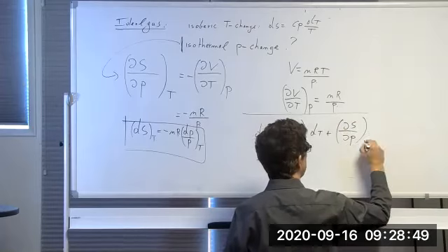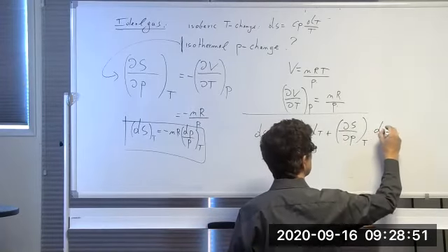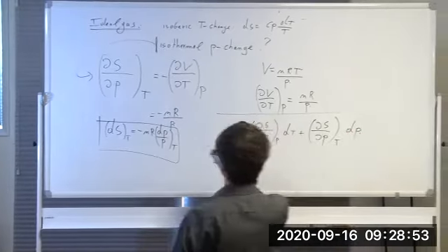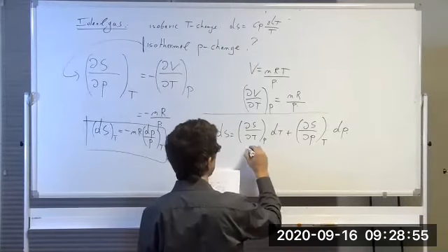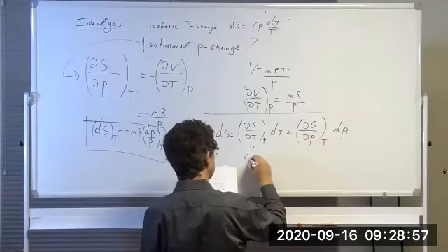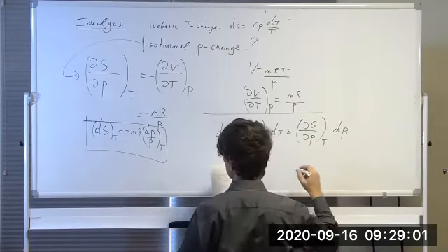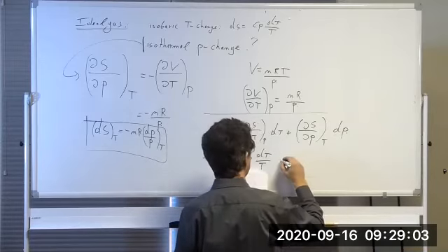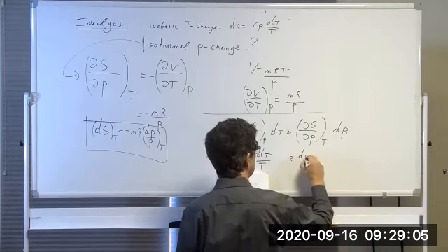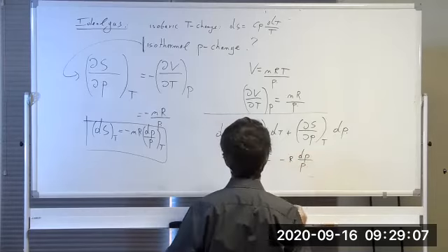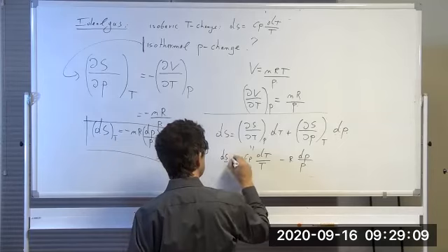Okay, this is just math, right? And I've just proven what that one is. So this one here, of course, is Cp. This is going to lead to Cp dT over T. And this one I've just proven. This is minus R dP over P. And I've dropped the n, so I'll write this as dS,